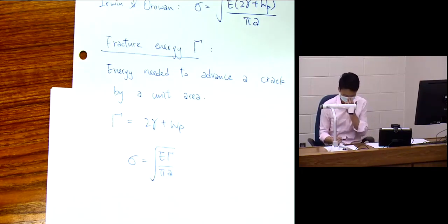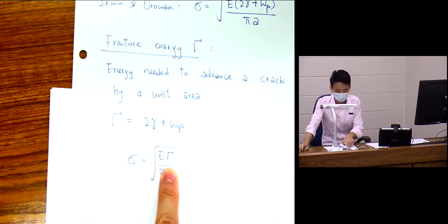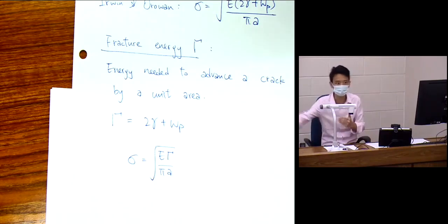So now, what is the significance of doing that? When we're dealing with a new material, we don't know what the associated fracture mechanisms are that provide the energy resistance to fracture. Writing that fracture energy explicitly in the equation allows us to not really need to know exactly whether it's surface energy or plastic deformation.